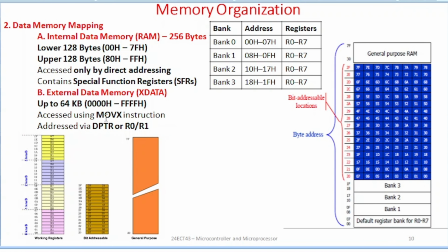Even though the upper RAM area and SFR area share the same address locations, they can be accessed through different addressing modes. Direct addresses higher than 7FH access the SFR memory space, and indirect addressing above 7FH accesses the 128 bytes of the higher range.